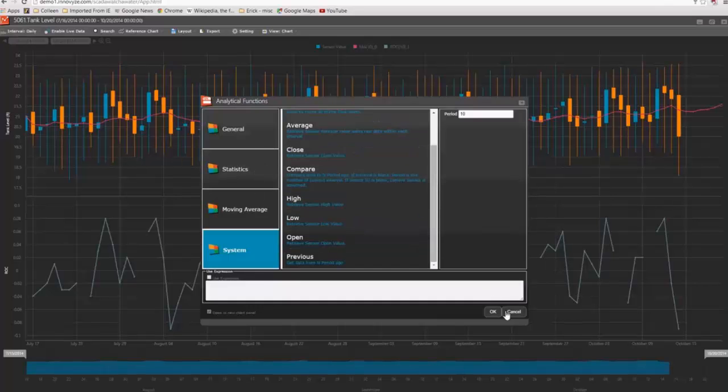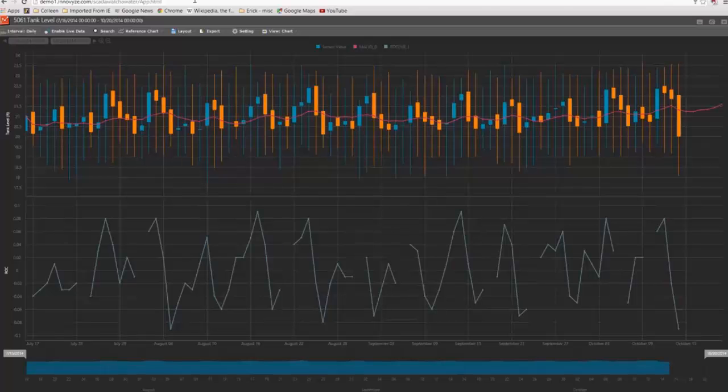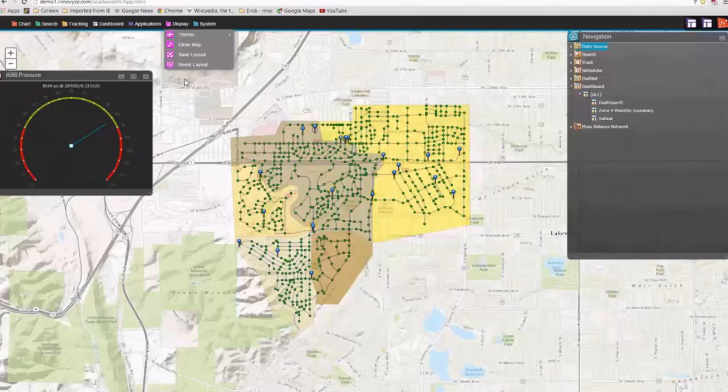And the idea with these is you'll be able to set them up and look at them in the short term, look at short-term operations, and also look at multi-month or annual operations, looking for trends and pressure changes and places where maybe this zone is trickling down in pressure over time, indicating that it might have some more leakage.